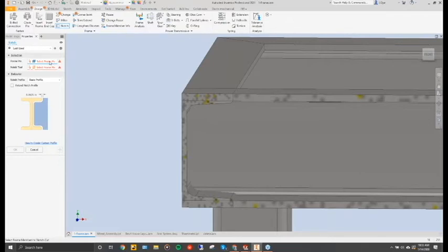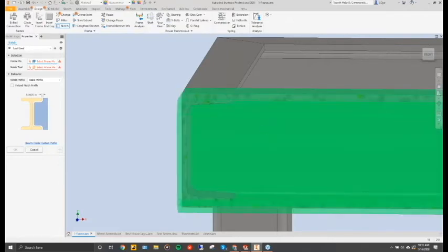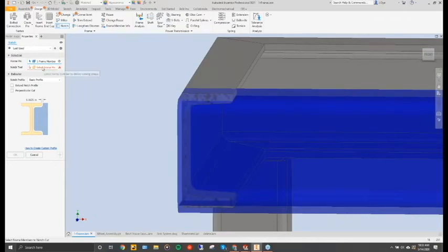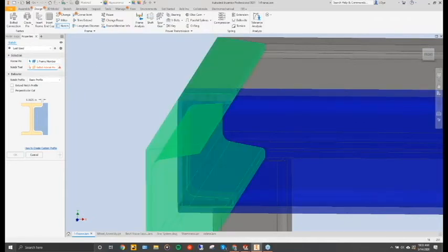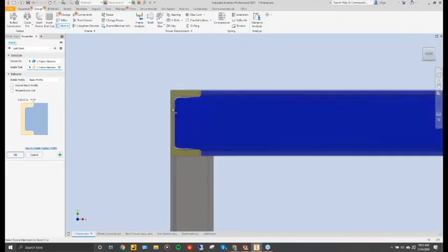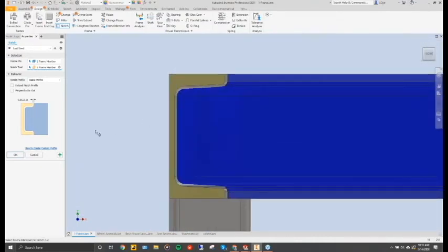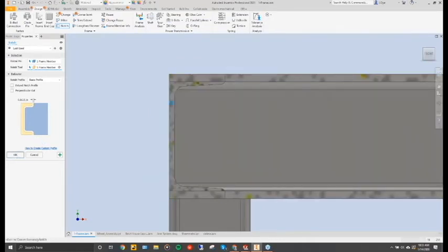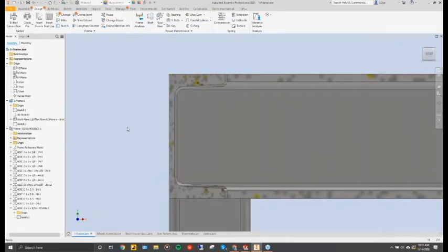And then frame member, select on that frame member, and then make sure that one's selected, and then select that one. And if I look at it from kind of the side view, you can see what the end result's going to be. In my dialog box here, you can see I have it set to 1/16 of an inch, right? So that's the gap that it's going to create for me right inside there.